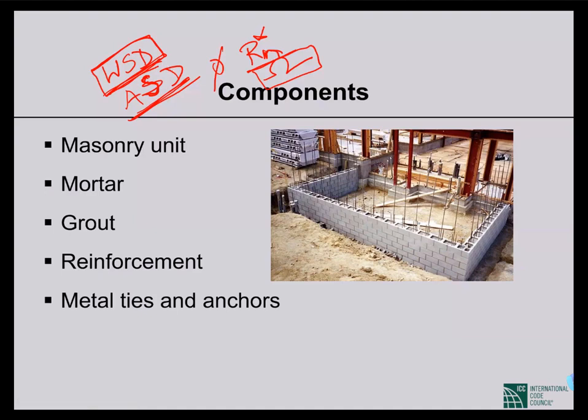Is there any code provision for number of stories in zone 1? The only provision is that the height to width ratio cannot exceed 2. The height can be double the width of the building. And there is no table that mentions anything for more than a 5-story building.